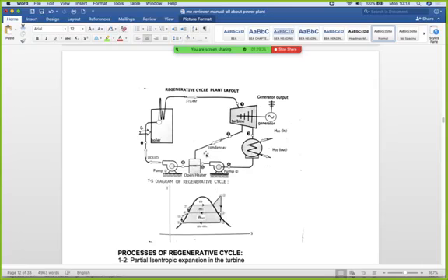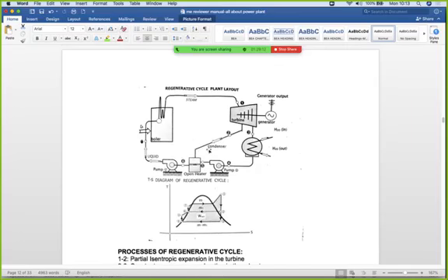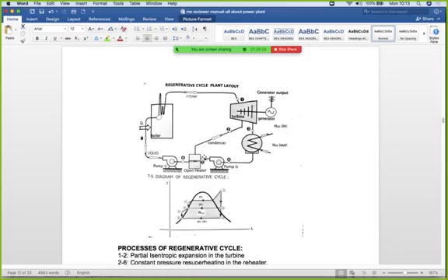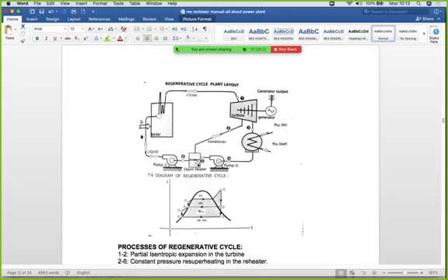So at the open heater there is warm water taking heat from the hot steam. The steam can be hot because it came directly out of the turbine. It did not pass through a condenser, so it could be considered as steam here. But it will take time to be heated in the open heater. So what will be pumped there is no longer steam, but a liquid. The liquid will be pumped again to the boiler.